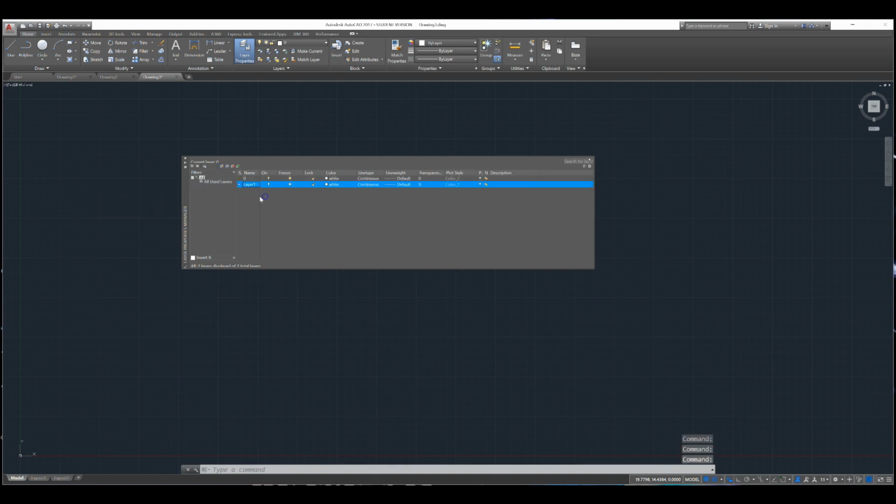So we're going to create a new layer. And you don't have to worry about naming your layers unless you absolutely want to. But what these layers allow us to do is actually change the colors. I'm going to show you how to change the color, the line type, and the line weight, because we're going to start working with two different types of lines called hidden lines and center lines. These are specific types of lines when you're doing your drawings that are not actually a part of the part or the object that you're creating, but they provide us with information.